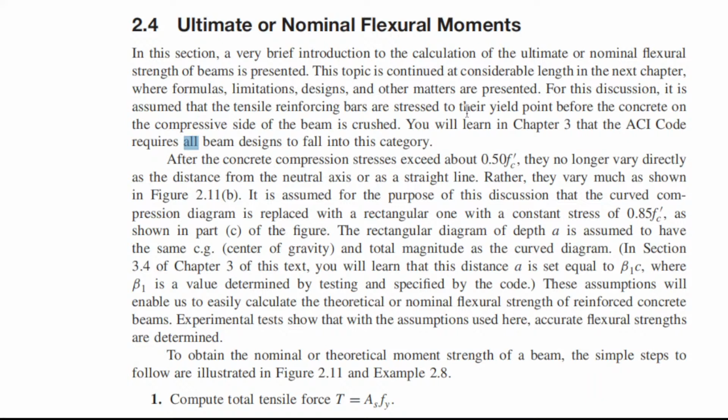Meaning, the tension reinforcing bar must be stretched to yield point before the concrete on the compressive side is crushed. So that is a very important principle.